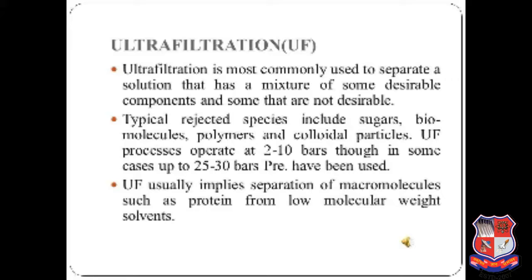Ultrafiltration is not fundamentally different from microfiltration, nanofiltration or gas separation, except in terms of the size of the molecules it retains. So normally different types of filtration units work based on size. Here, different pore sizes of membrane material are used for the separation. The pressure is also different, their sustainability capacity is different, their permeability is different, and the retentate capacity is also different.